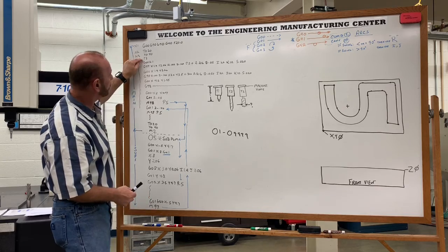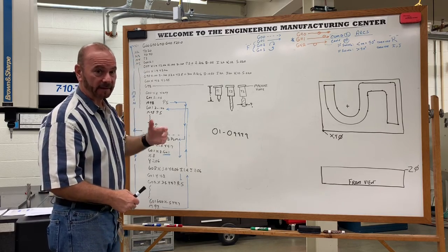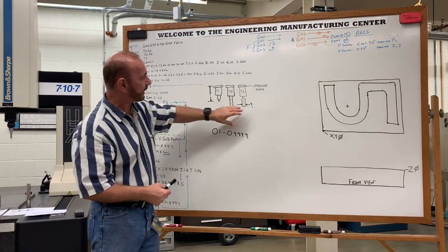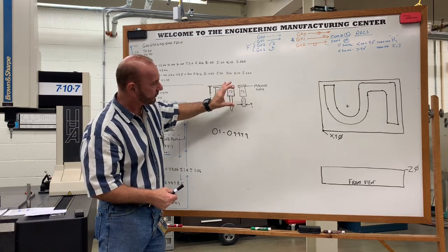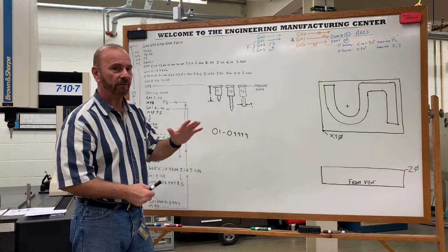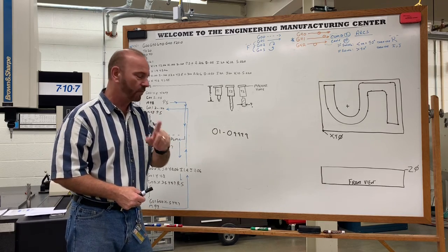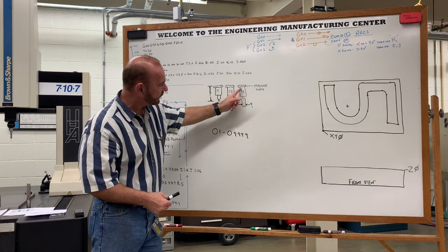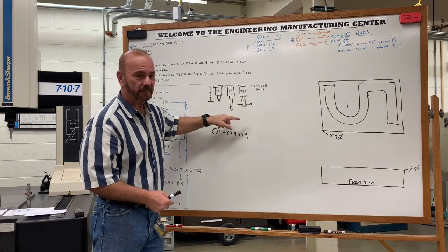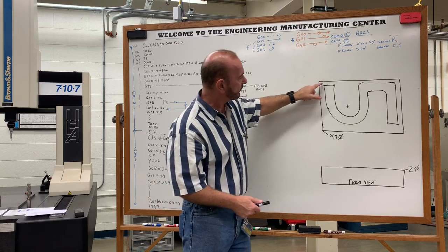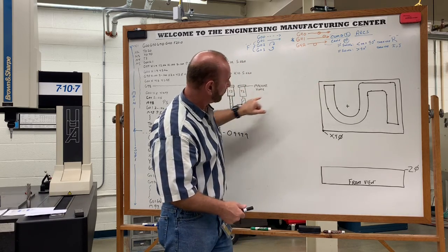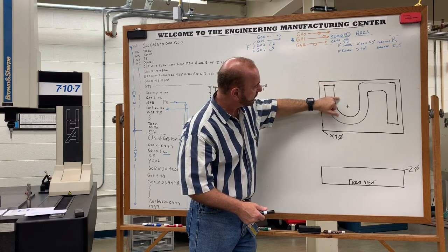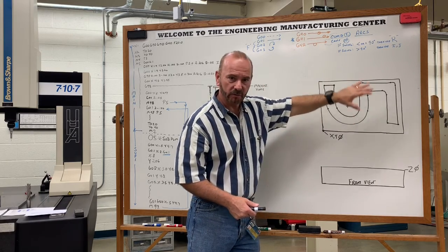When the tool is called up in the program, again, it's a modal switch, so it turns on, it reads that information. What is the diameter of this tool? What is that tool's length? And it applies it to every move that you program. So you as the programmer are only programming these little tiny blue dots, which is the center line of the tool and the tool tip. And you're driving that from this center line over each one of these points, either in a G01, a G02, a G03, as you walk around the part.